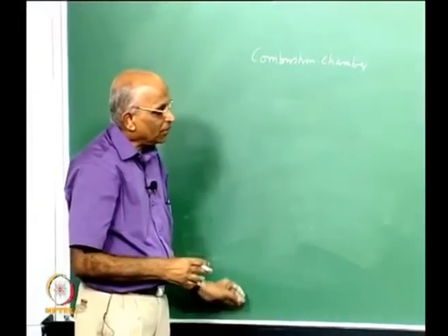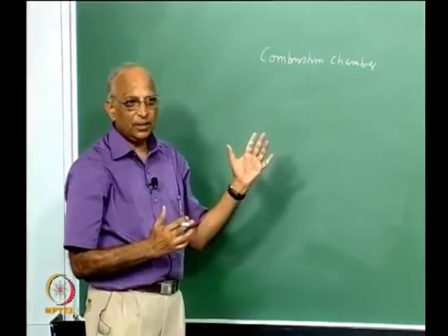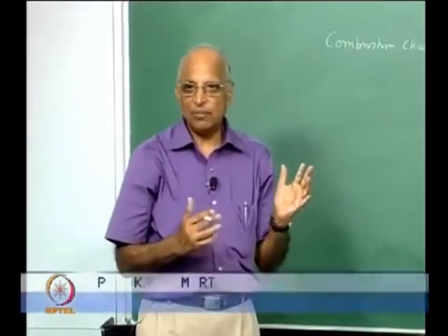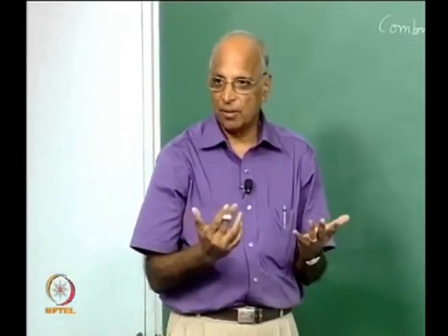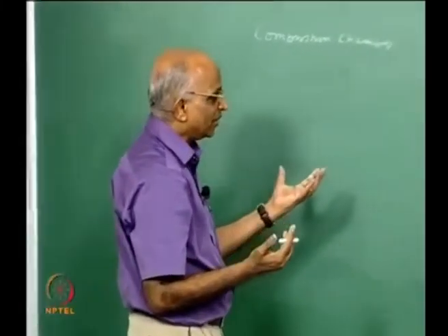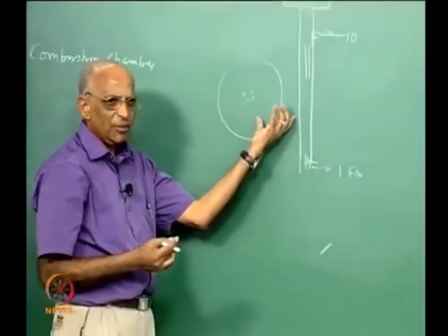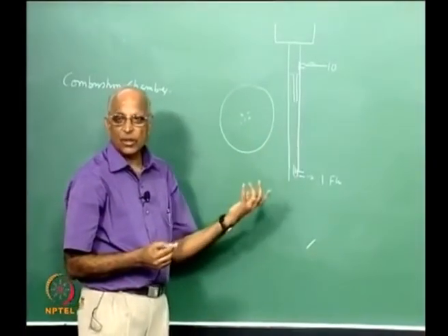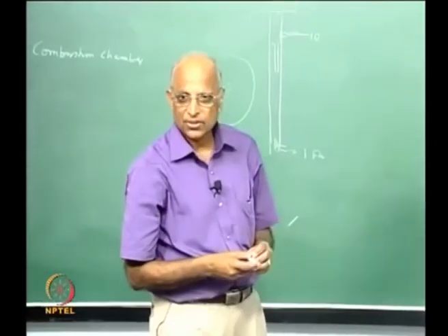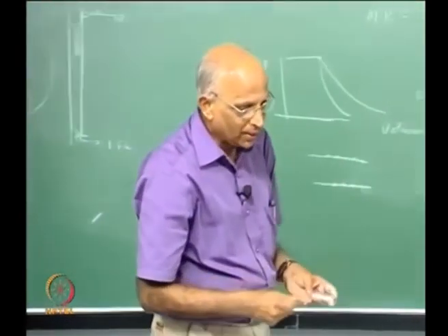Therefore, in this class what have we done? We started with the gas generator cycle. We looked at the deficiencies of a gas generator cycle, namely that some propellant gets wasted and is not fully utilized. Therefore, a staged combustion cycle and an expander cycle are preferred, especially at high pressures. Then we just started with the injectors, and we looked at the shower head injectors. Maybe we will build upon this and look at the other injectors which are used in liquid propellant rockets in the next class. Well, thank you then, I think that is about it.